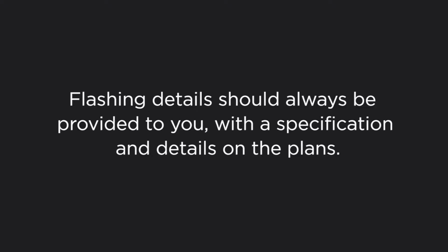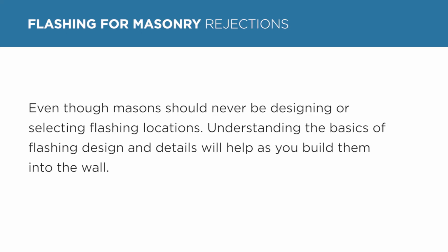Flashing details should always be provided to you with a specification and details on the plans. Even though masons should never be designing or selecting flashing locations, understanding the basics of flashing design and details will help as you build them into the wall.